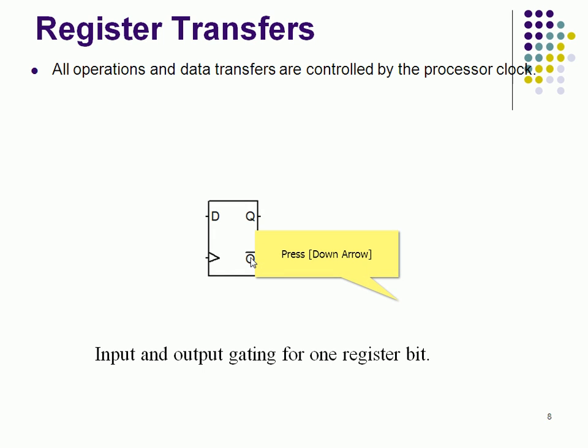There is a D flip-flop which helps us store the data. It will keep the data and give it out as it is when the clock is supplied, right? When the clock is supplied, whatever data is coming will be stationed and produced. When the clock is disabled, no new data will be accepted, and the data will be locked here. If you supply 1, 1 will be maintained and produced. If you supply 0, 0 will be maintained and produced. That is the property of the D flip-flop we have discussed, right?